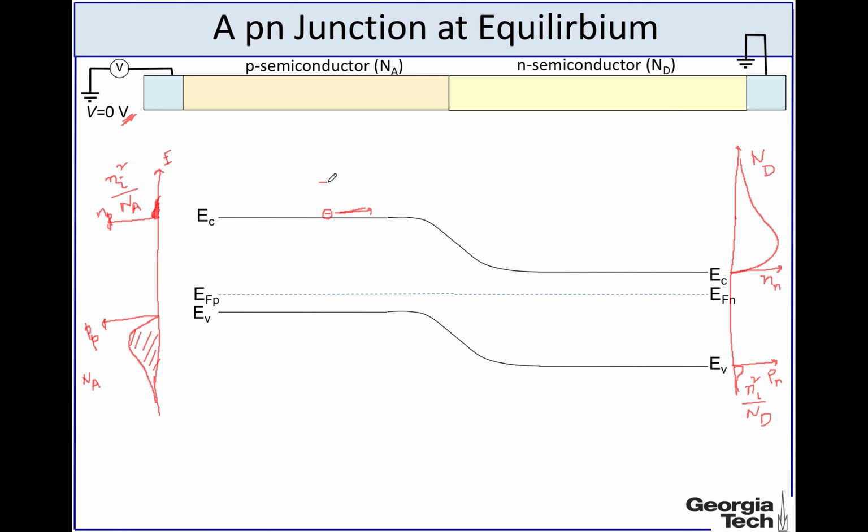So we call this current density Jn, moving from N side to the p side. This is the first component of current which flows from N side to p side, simply because there is this barrier and the N side has a lower energy for the electrons, so this will try to move that side.